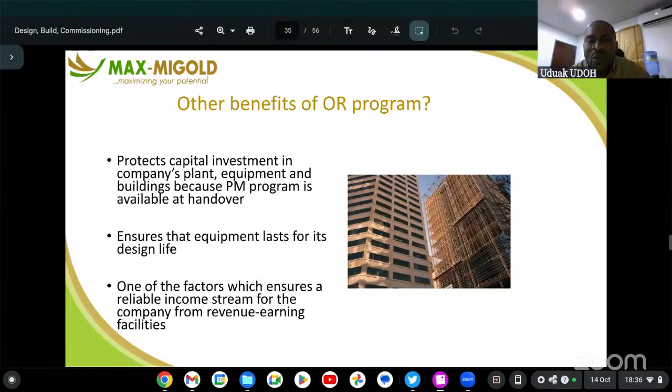So when we are operationally ready on site, guys, our equipment will last long. Imagine you washing the AC filter every 2 weeks. It will last long because it will be breathing well. Imagine flushing the drain every 1 month. There are some ACs where you know that, okay, this AC, where it is located, has numerous doors going in there and numerous end users.